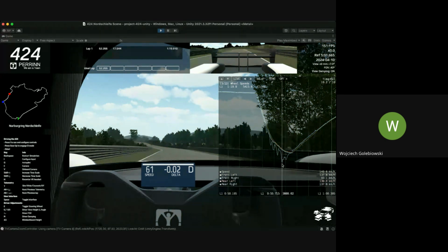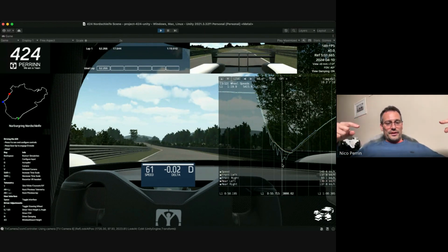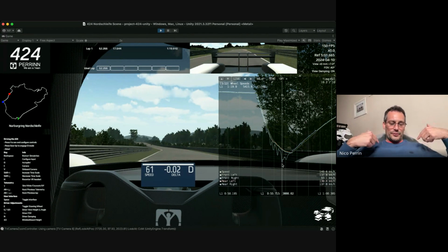Okay, and you also talk about locking the diff. How is the diff physically locked? The diff is like a clutch. It's got plates, like a clutch, it can be 6 or 12. There is a drive shaft coming from the left and the right. Each wheel has a drive shaft, and what connects the two drive shafts is a clutch between them inside the diff, and then there is the bigger outside wheel with the gear that connects to the motor.